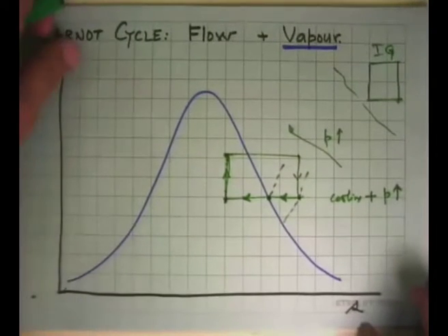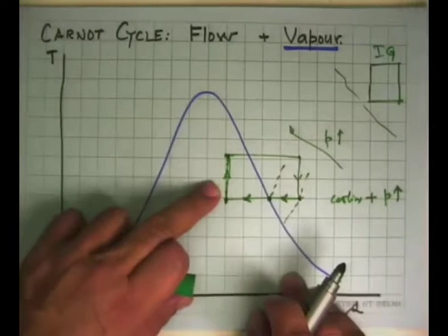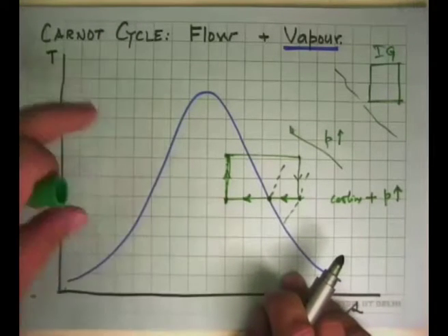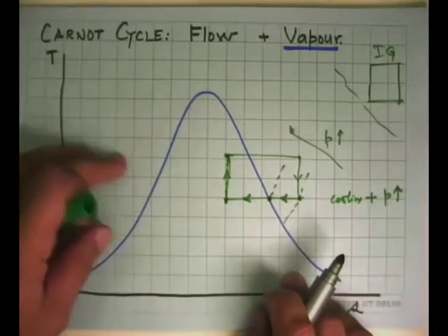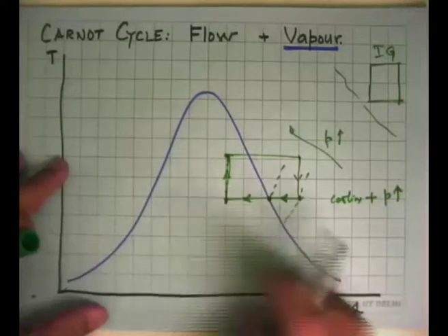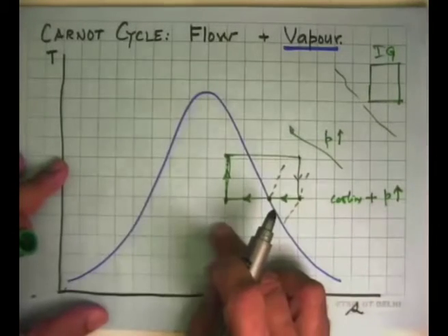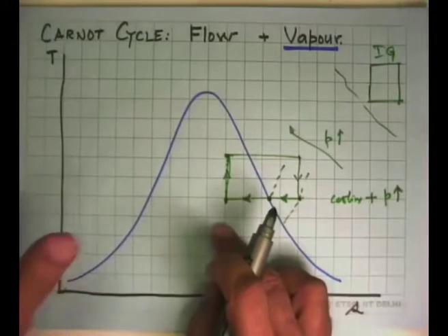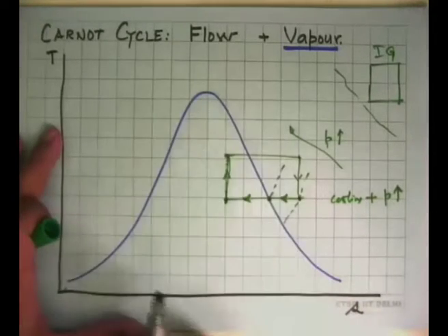And we just said that if you are going to make a compressor or a pump or anything, it has to either handle only a liquid or it has to handle only a vapor. This is handling completely a wet mixture. In the real world, we cannot make such a thing. So this is not possible.